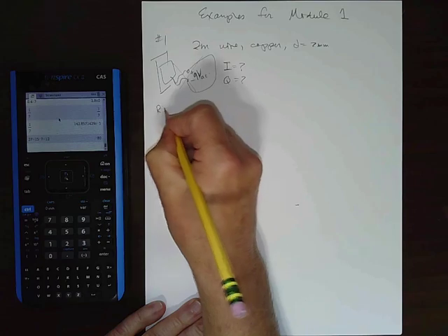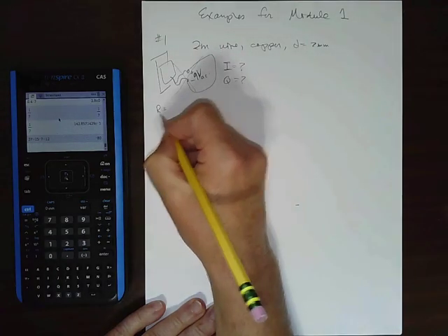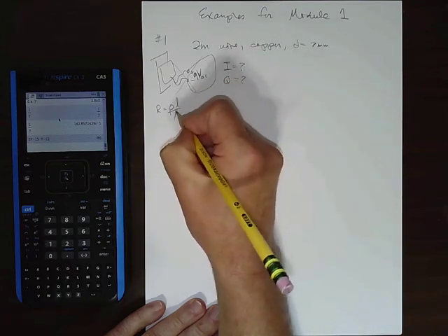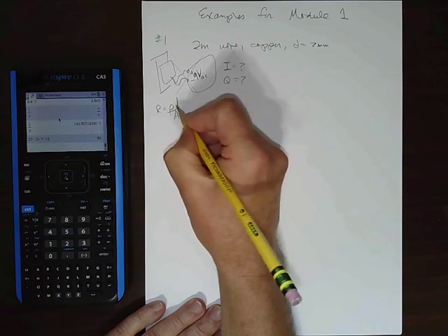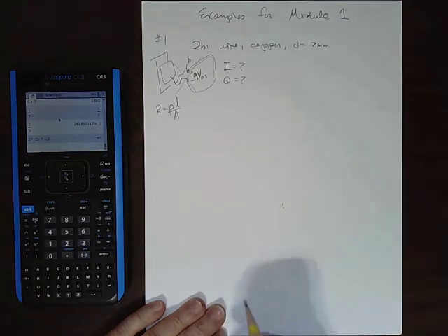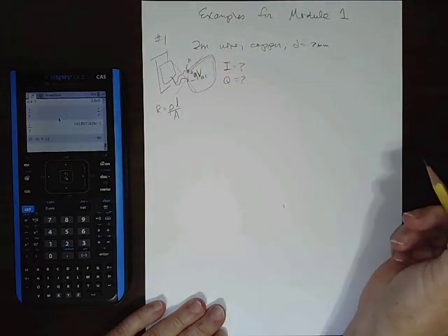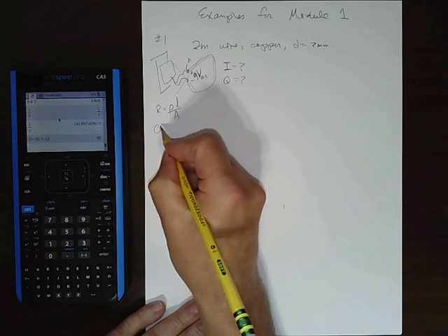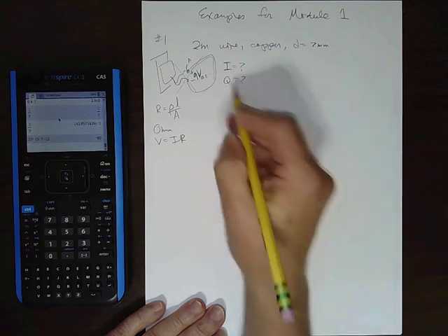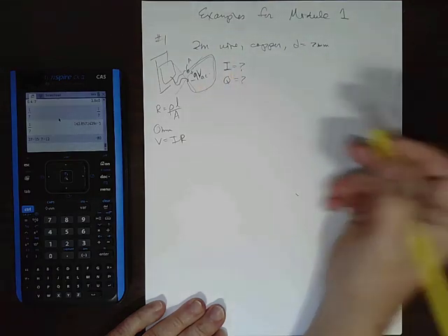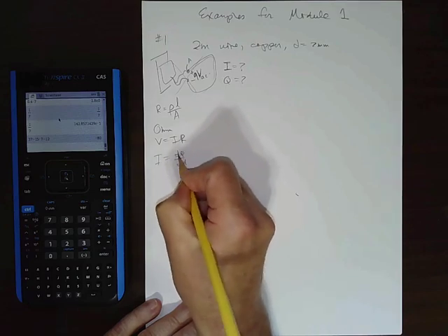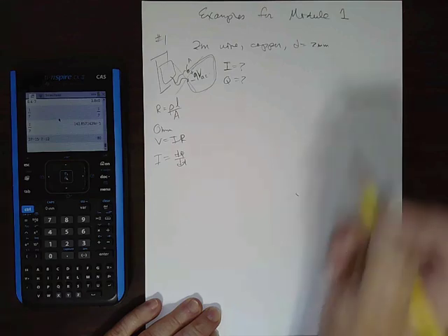So one thing we're going to need is just the equation for how do you get resistance from parameters of a wire. So it's R equals rho L over A, where rho is a resistivity, A is a cross-sectional area of the wire. So if this is the wire, it's got a cross-sectional area A in there. L, of course, is the length of the wire. R is its resistance. We also need Ohm's law. It says V equals IR. Remember our good old friend to relate V and I to each other, and R. And then just from the definition of what is current, we need I is dq dt. Remember that also to get back to charge probably.